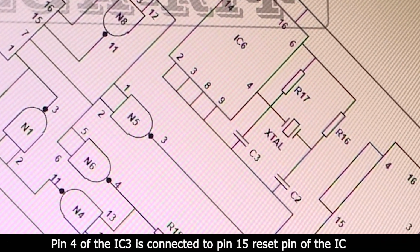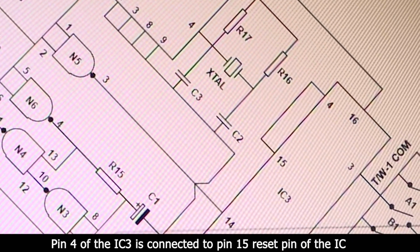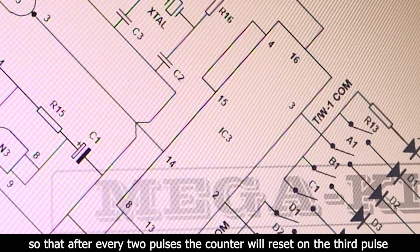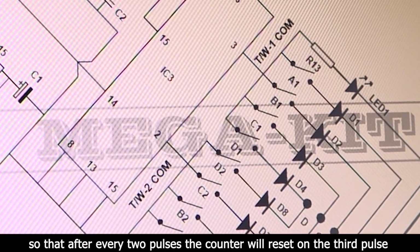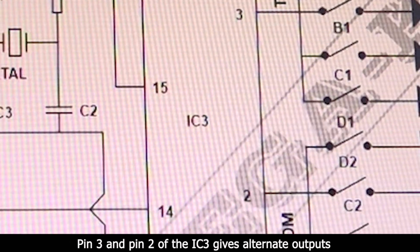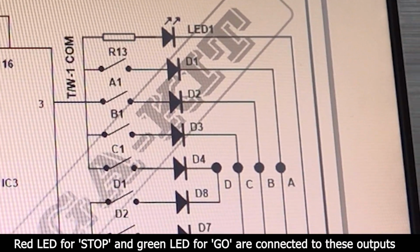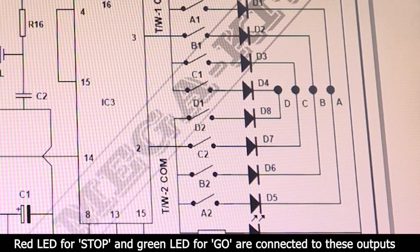Pin 4 of IC3 is connected to pin 15 reset pin of the IC, so that after every 2 pulses, the counter will reset on the third pulse. Pin 3 and pin 2 of IC3 give alternate output. Red LED for stop and green LED for go are connected to these outputs.